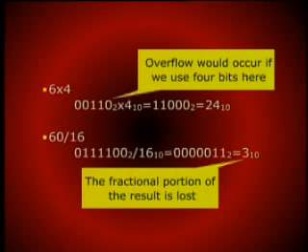Now please note that we have used 5 bits to represent this number. Had we used only 4 bits, then the second shift would correspond to an overflow. So overflow could occur if we use 4 bits for this example, or if the number of bits is limited by the number of bits in the register, the overflow has to be taken care of.